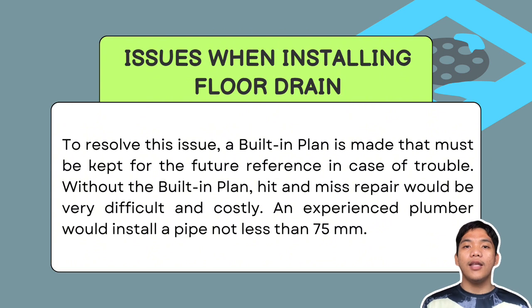is alam natin kung saan tayo mag-aayos. Saan natin aayusin yung bagay na yon. Experienced plumber will not install a P-trap or sabihin yung house trap ha, smaller than 75 mm diameter on the floor drain. So ito na nga. So kung kanina, 'di ba, kaya nagkaroon ng problem doon sa P-trap is 50 mm yung ginamit niya. Dito, ang sabi is, kailangan talaga, hindi dapat bababa pa sa 75 mm yung size ng pipe para hindi magkaroon ng pagbabara doon sa pipe.